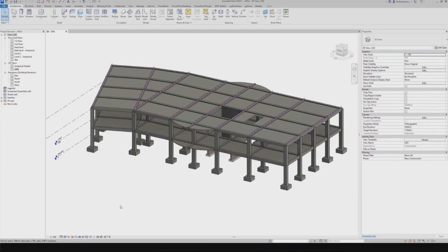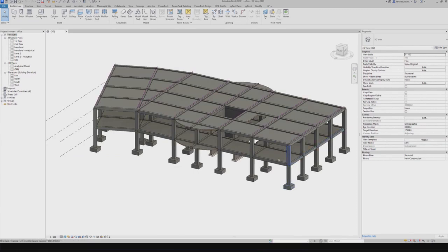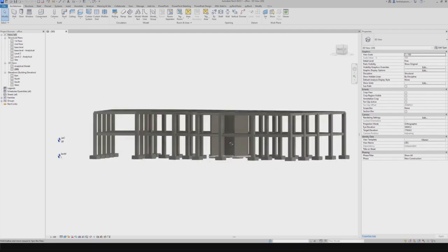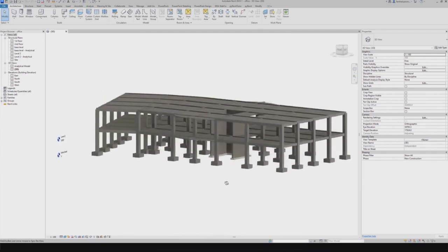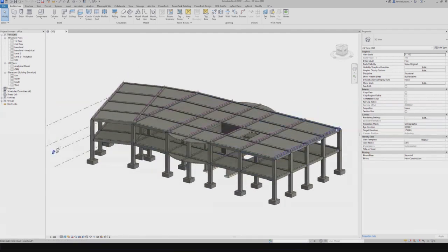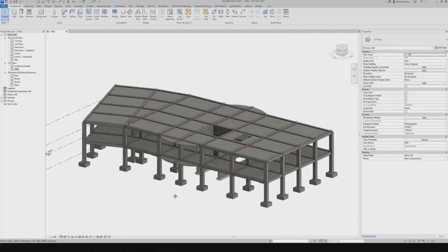Okay, I have opened the concrete project in Autodesk Revit. As you see in this project, I have different elements. I have foundations, columns, beams, slabs, and even shear walls, as you see there. As well, I have some loads already applied to my Revit model. So we can start by exporting this model directly inside Advanced Design, which the process is actually very simple.